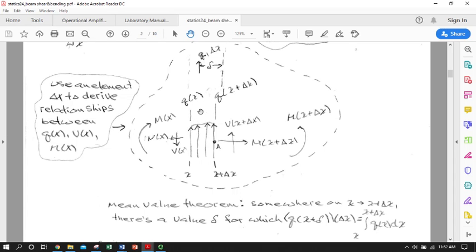It would be really nice, if we wanted, backing up a bit, to write the equations of equilibrium. With the exception of that distributed load, everything's pretty straightforward. If we looked at the sum of the forces in the x direction, we would just have N at x plus delta x minus N at x. And then our y forces would be negative V at x plus V at x plus delta x plus the integrated distributed load between x and x plus delta x.